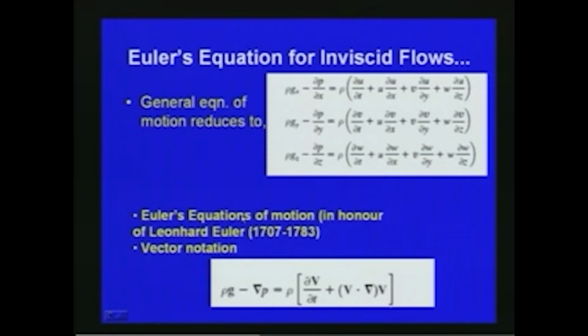Now, as I mentioned, Euler's equation is one of the fundamental equations of fluid mechanics. Even though here we consider the flow as inviscid, many practical cases like water flow or air flow we can approximate as inviscid and then try to get a solution. The advantage is that these equations are simple, and the solution will be much easier if we do not consider the shearing terms here, but it is an approximation.